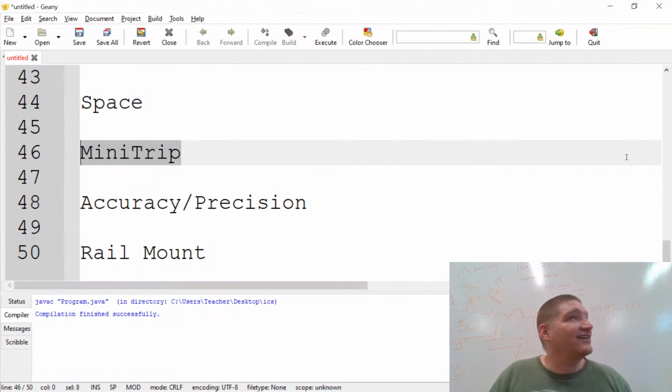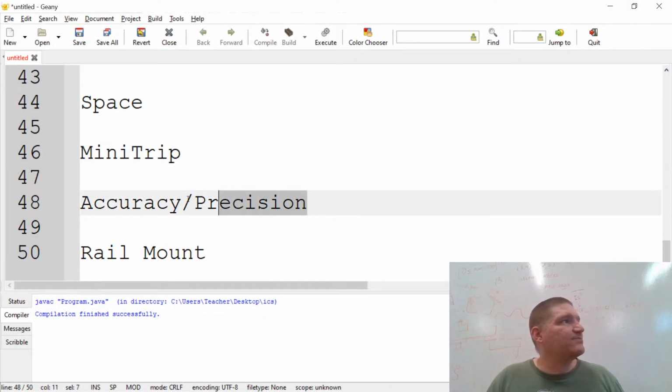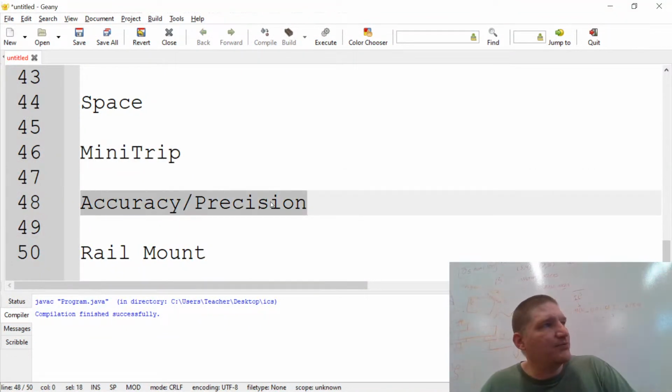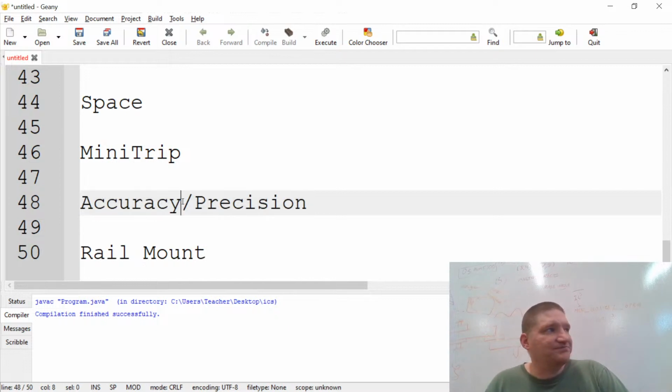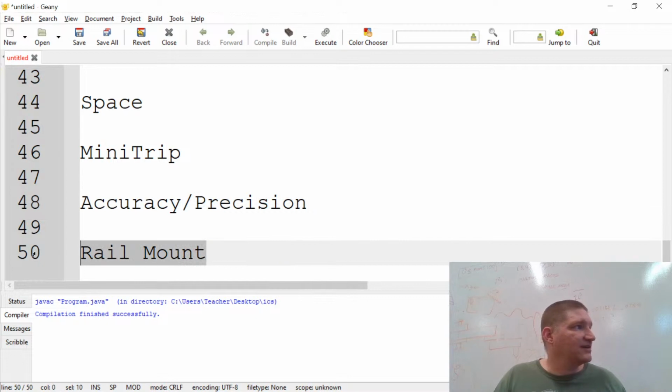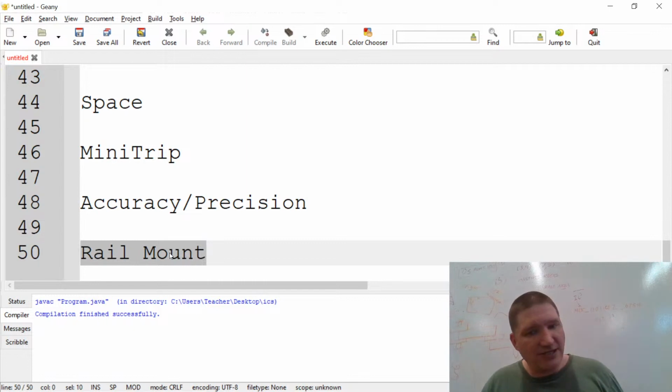All right. Okay, I'm getting close. Okay, accuracy, precision. I don't know. Precision, I get from design, so I'm going to have the same precision that any other 3D printer has, positioning wise. Accuracy, I should have repeatability, and I should be able to calibrate everything. I should have as much accuracy and precision as I want. It shouldn't be a problem. I just have to go slow and calibrate. That's pretty much it. And screw that rail down to the table. A lot of people are just like, hey, it's going to twist. So anyways, there we go.